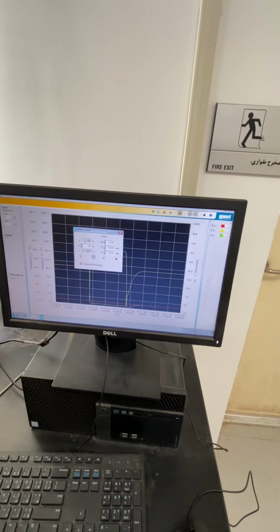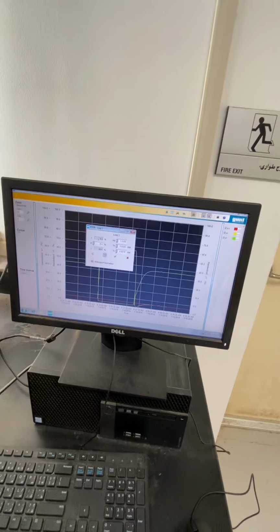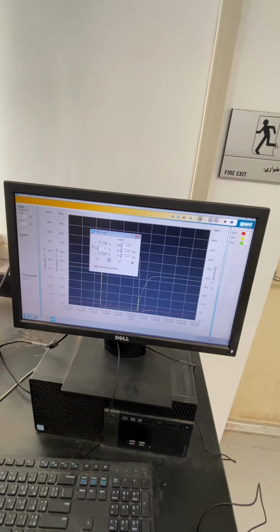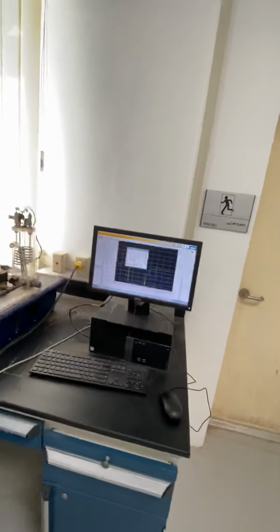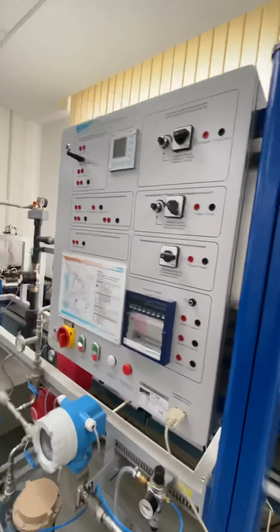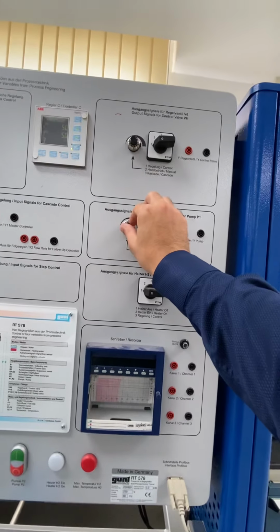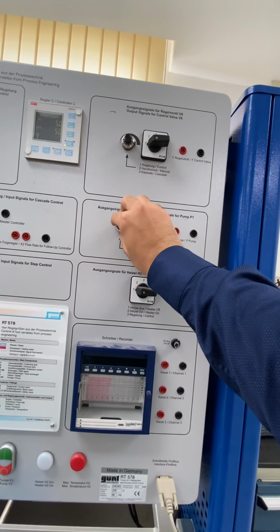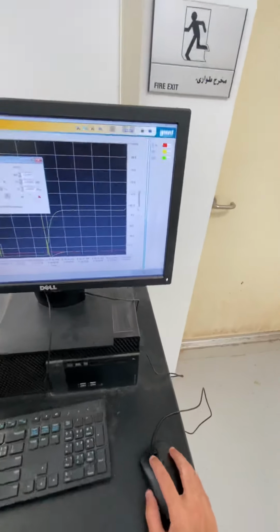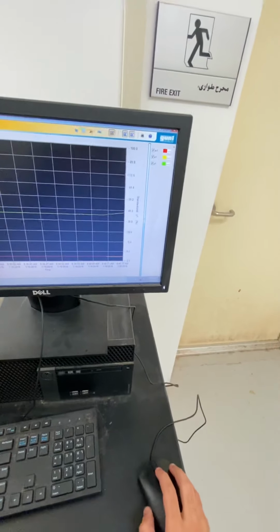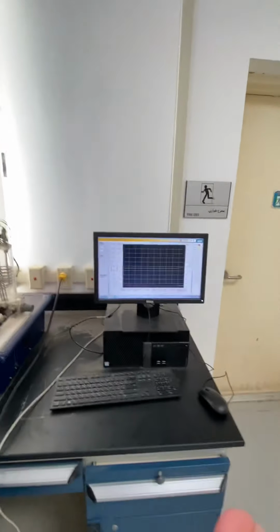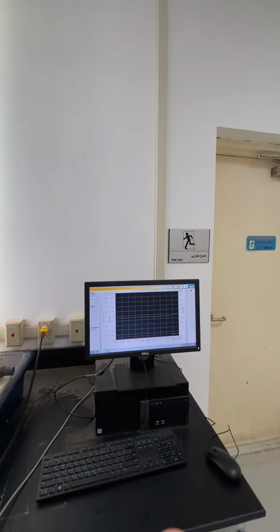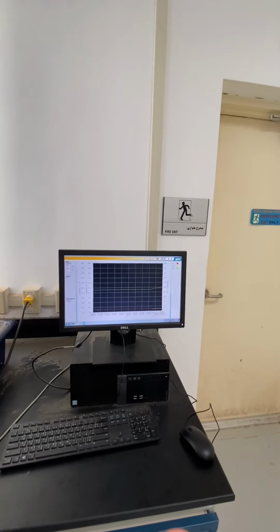Now we are back again at the process value of 5%, and it is equal to the set point specified in here. So if we play with pump speed by adjusting this knob right here, you will see that I reduce pump speed. You will see right away that we have a slight drop in the process value. Okay, and let me make a significant reduction, like so, just to make it clear for you.